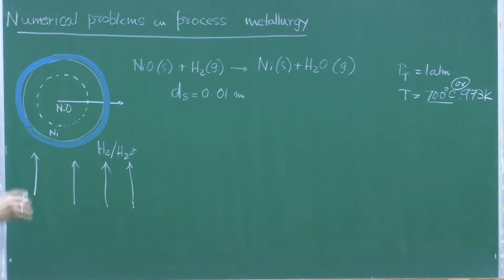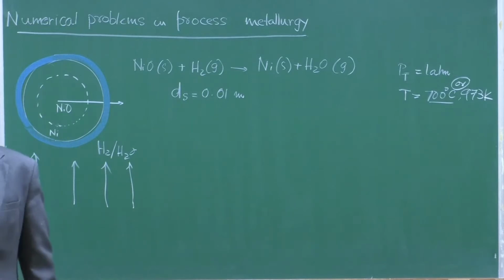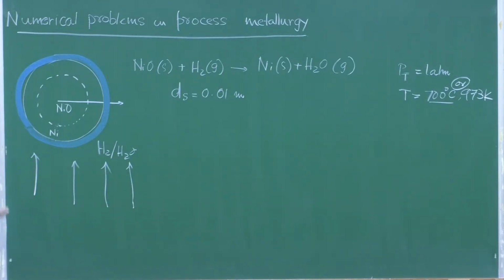Okay? And of these 5 kinetic steps, one could be rate controlling, more than one step could be rate controlling, and we can say there is a possibility that the process is either mass transfer controlled or chemically controlled or mixed controlled. And I want to now demonstrate through these problems, depending on the nature of the rate limiting step, how the mathematical treatment would vary. Case 1.